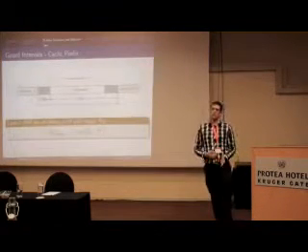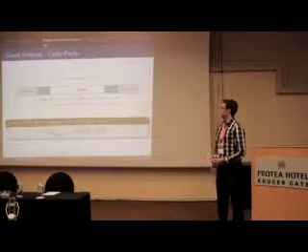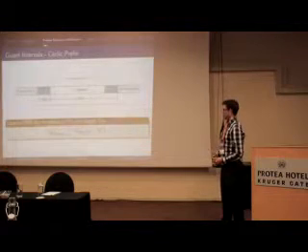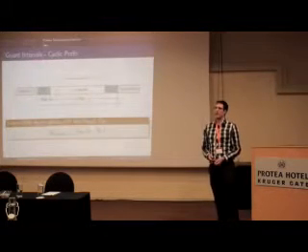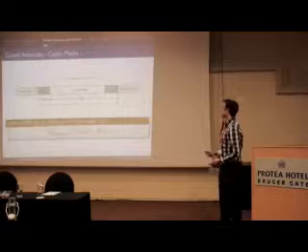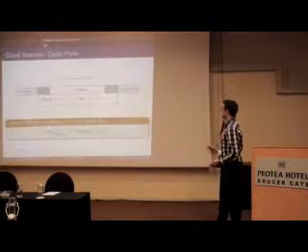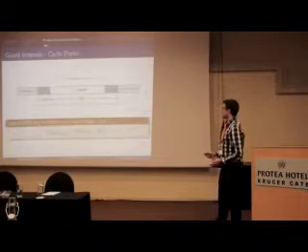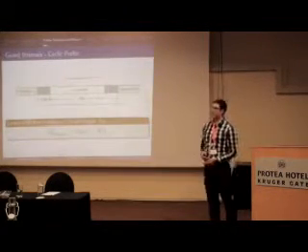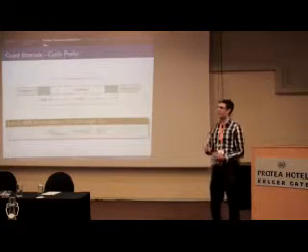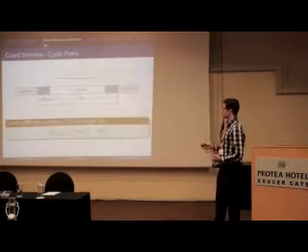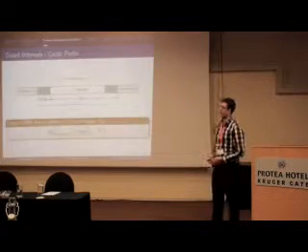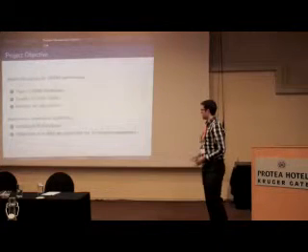Another important factor for OFDM is the idea behind the cyclic prefix. This is used in order to reduce the effect of intercarrier interference. The idea behind this is we'll take the last data of a symbol, copy it, and place it at the front. So what this will do is, if two symbols arrive in a small period at the receiver, we can simply ignore this first part and still be able to retrieve the whole of the symbol.